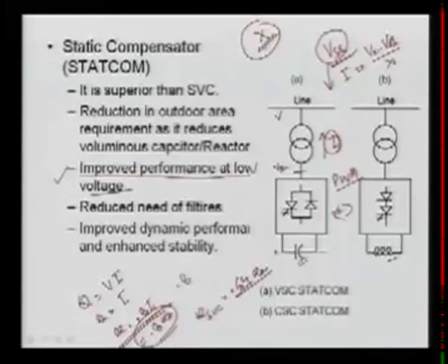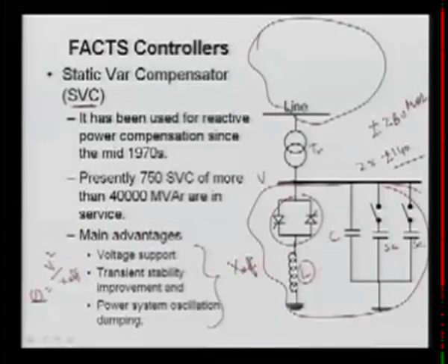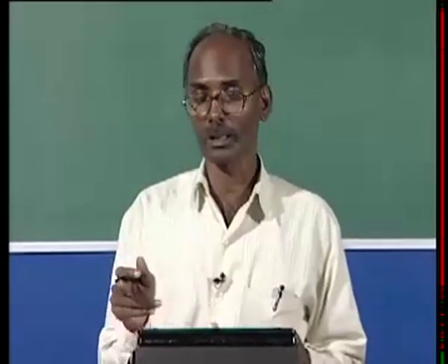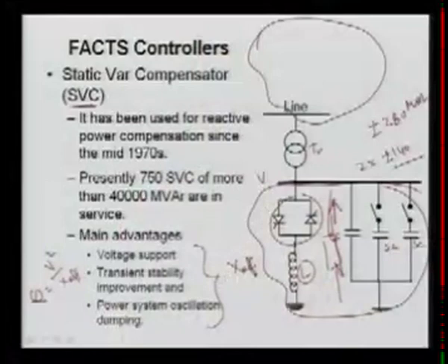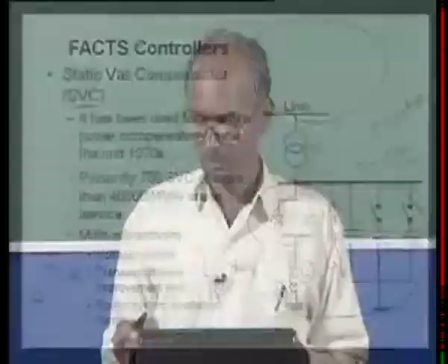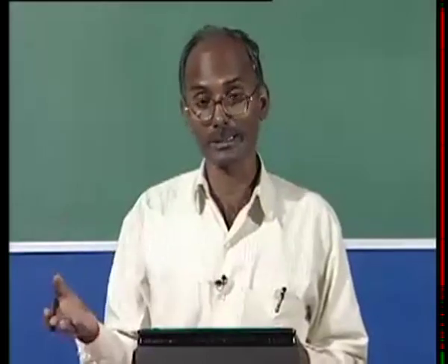So this is a voltage source device, and that is a variable impedance device. Here we can generate this voltage source with the fundamental frequency, so there will be no harmonics. So the need for filters is reduced, though wherever required we may still use some filter. But another advantage of SVC is that if you put filters at the fundamental frequency, they provide reactive power at the fundamental component. So these filters are sometimes very advantageous, as they inject reactive power at the fundamental. However, for harmonic frequencies they will work as a filter and shunt them to the ground. But again the cost will be more, since you are putting in another extra device.